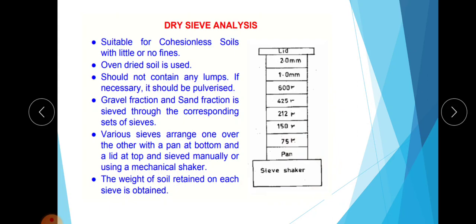Okay, so sieve analysis may be dry sieve analysis or wet sieve analysis. Dry sieve analysis is suitable for coarse-grained soil with little or no fines, and here for dry sieve analysis, usually oven-dried soils are used without any water content.